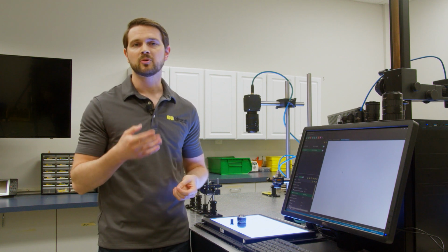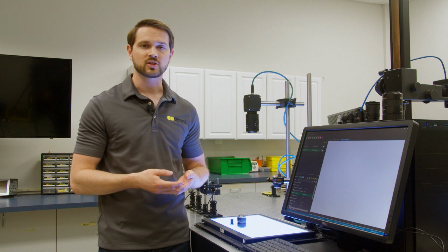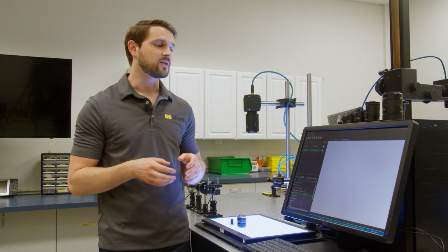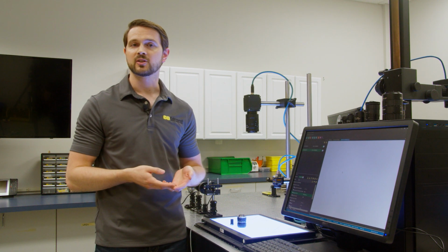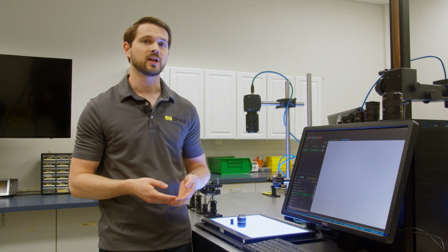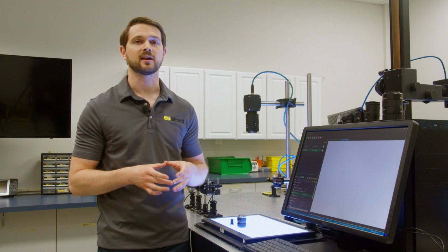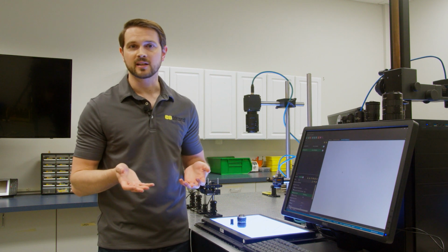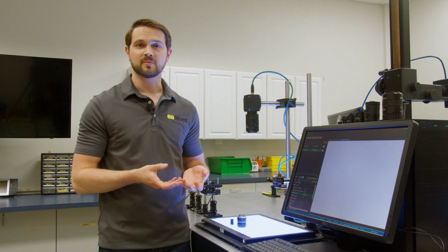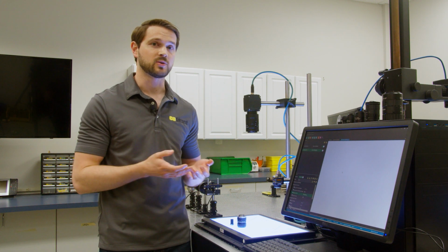That's what we would put on our lens spec sheet to say that this covers that 1 inch. Now, if you look at the actual nominal dimensions of a 1 inch sensor, they're 6.4 millimeters by 4.8 millimeters, with an 8 millimeter diagonal. I'm pretty decent at math, not the best, but it's impossible to make any of those numbers correspond to half an inch.